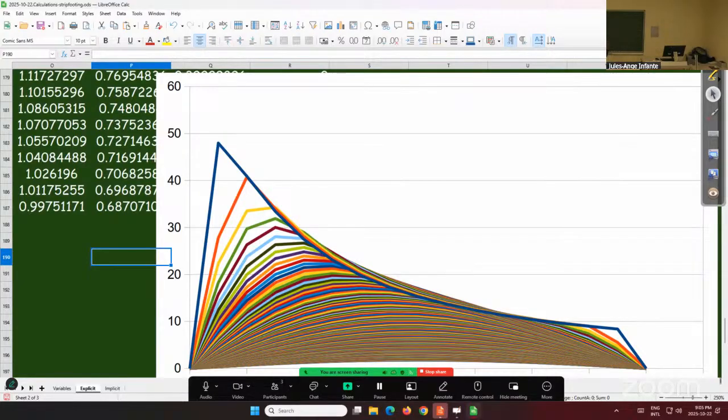So I guess we see what it's all about. It's interesting that you see that we do get a crossover of the pressure, right, as it balances. So that's an important thing to keep in mind as an engineer, though, that over time you will not always get the decrease everywhere of pore pressure, right? As pore pressure dissipates, you will get in some areas near the center an increase in pore pressure that will be higher at times further down the road than it is at time 0.